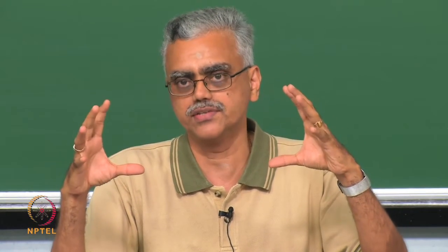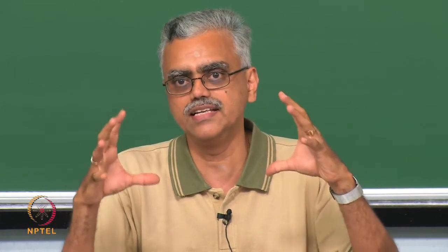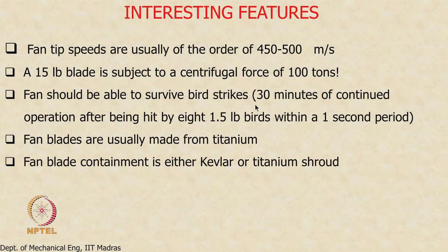Now on top of that, there are also very stringent safety restrictions because the cross sectional area of the fan is very large. It is also more prone to bird strikes. As the area increases, the probability of birds hitting the engine also increases naturally, right? So it should be able to survive bird strikes, that it should be able to operate for 30 minutes after being hit by 8 birds within a 1 second interval. So it is tested for such stringent conditions.